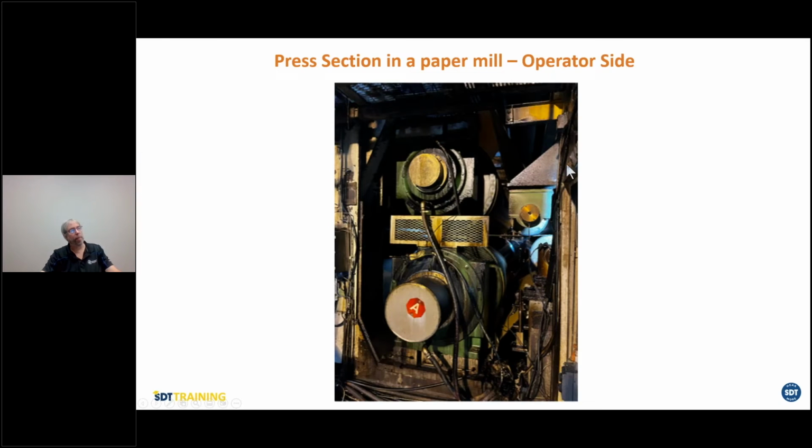First of all, this is a paper mill, the operator side. These are presses on the paper mill. Presses have basically a layer on top of them, which erodes with time. So every once in a while, they have to remove the rolls and put ones with new covers on. In this particular instance, when they moved the presses up and down, there was a hydraulic motor which failed. So it dropped down, boom. They screwed up two bearings. So they had to take two old rolls and put them back on until they get those fixed.